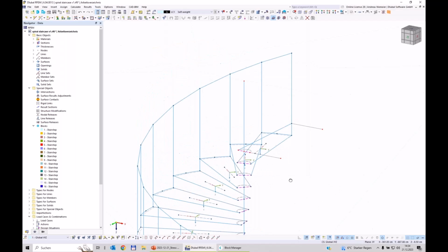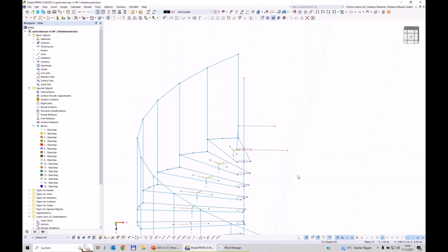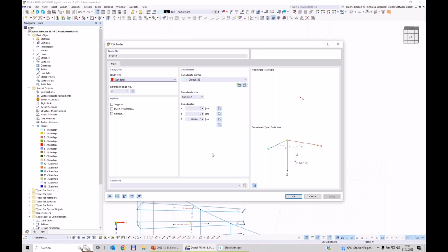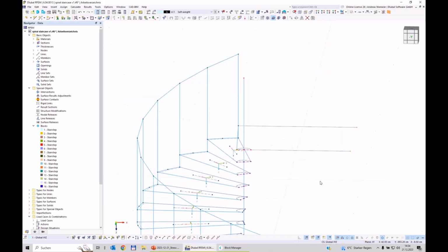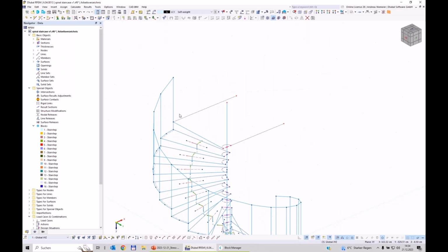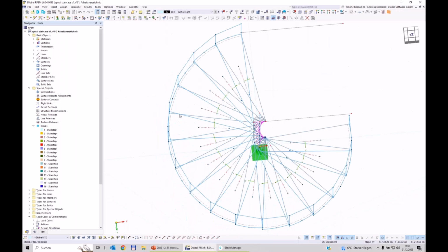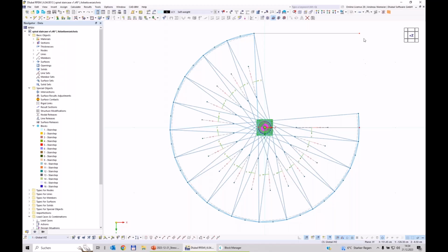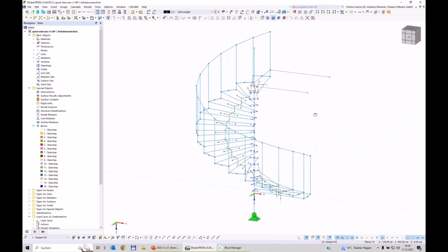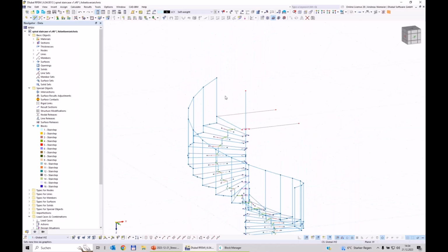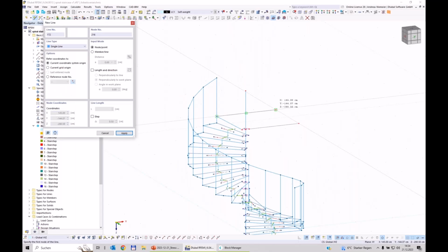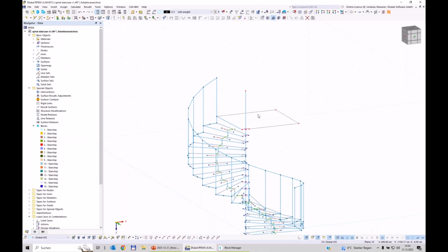And you see now we receive this, let's say, level geometry, and I can place now both nodes with the dimension of 145 centimeters. And here, when we get the view from top, you see they are ending directly on this place here. And these nodes we connect now. So I use here both nodes and have now a geometry of this level.